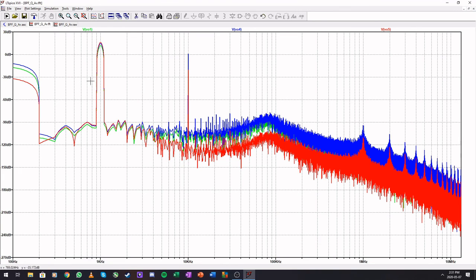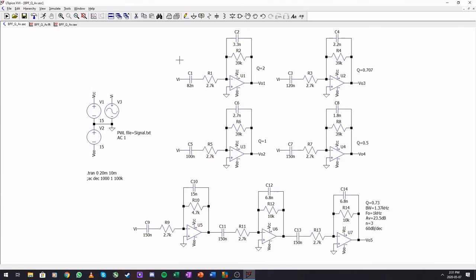So yeah, the best for bandpass will be to go for a higher order or to rather go for a high Q filter. So yeah, this is typically not the best way to do widebands. This is in general for very wideband filtering.